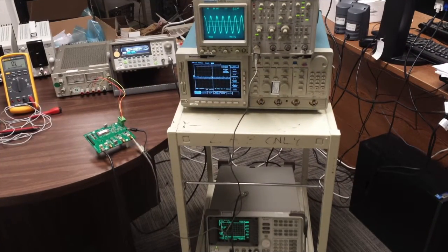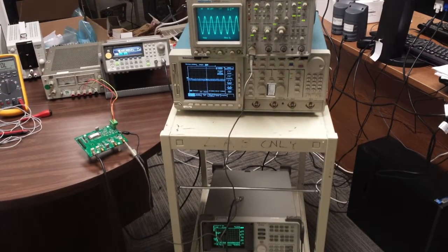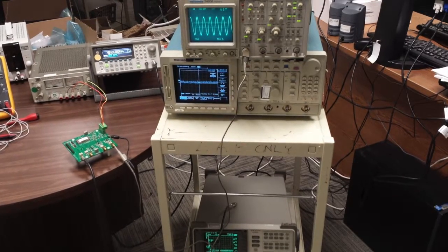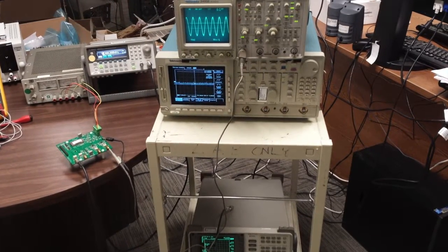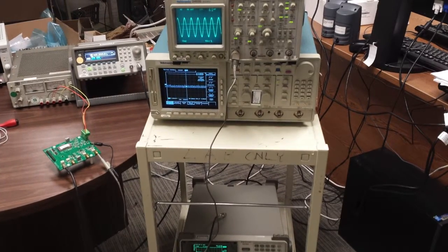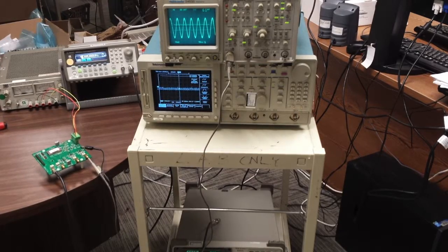Various laboratory setups were constructed to measure the filter's performance. This photo shows a simple setup where a signal generator passes a 10 MHz signal through the filter, and it is monitored at the oscilloscope. The 10 MHz tone passes through the filter unattenuated since it's in the passband.